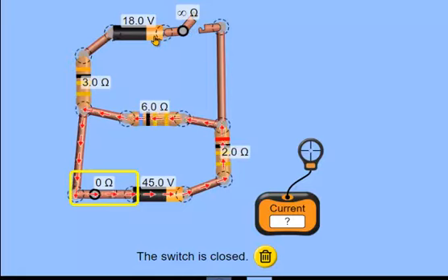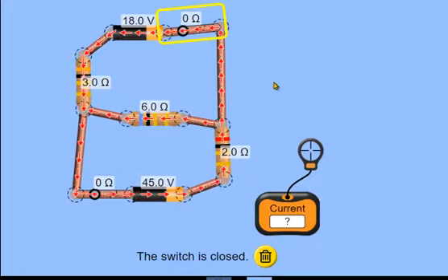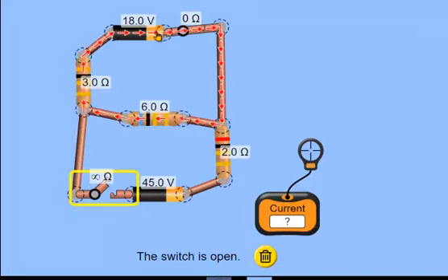And notice that on the top, in just a moment, when I turn this one here, even though I have the positive terminal here, the current is not going to flow to the right. Watch. There we go. It actually flows in the opposite direction of the battery. Notice when I open the switch at the bottom here, that's not the case. Now it really flows in the direction it's supposed to. But with these two switches closed, the 45 volts is just too powerful here, so it actually pushes the current in the opposite direction.